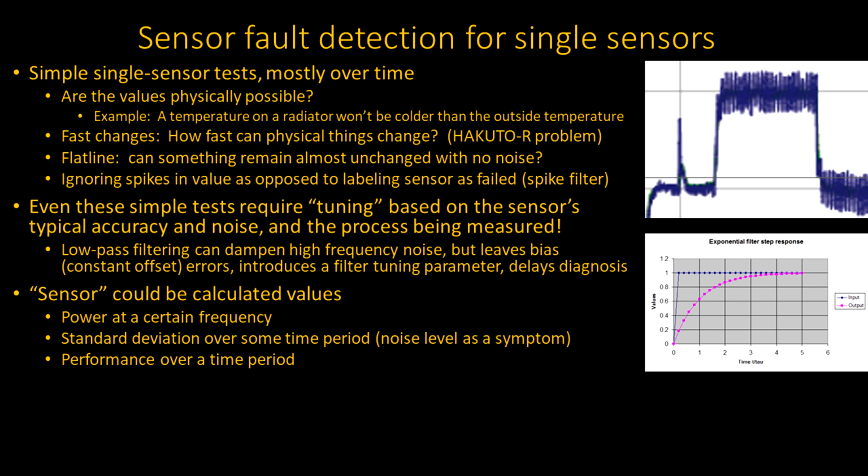Now, a word of warning about all these things. These tests are really simple, but they do require tuning, and that's based on the sensor's typical accuracy and their typical noise, and also the process being measured. So, for instance, looking at that graph on the right-hand side where you had a lot of high-frequency noise up in the center of the graph, if that's normal, you better be careful that you recognize that a rapid change over a very high frequency is actually okay.